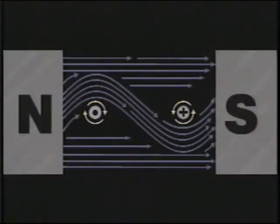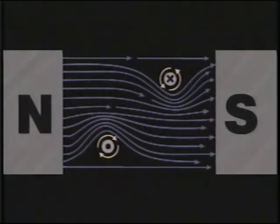The alternating direction of current flow in the U-shaped armature allows the motor to put magnetic flux line interaction to work. Here's how. On the left, the armature flux lines distort the field flux lines, and magnetic push moves the armature downward. At the same time, the armature flux lines on the right also distort the field. Here, because current is flowing in the opposite direction relative to the permanent field, flux line interaction causes the armature to be pushed upward. The U shape of the armature creates two opposite flux line interactions that combine to push or rotate the armature within the permanent field.